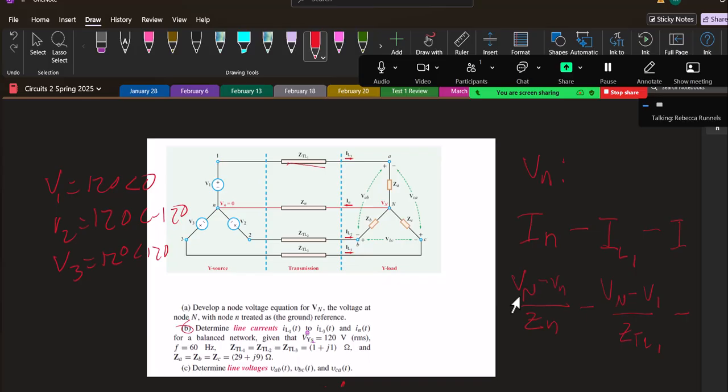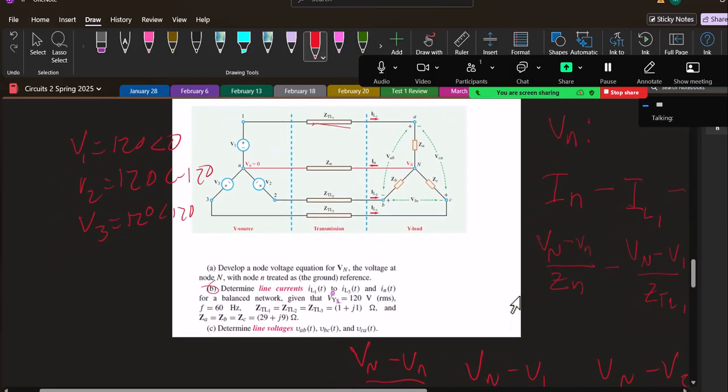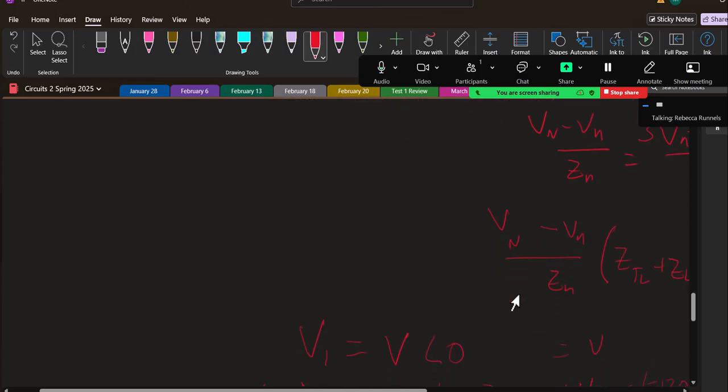I want the voltage between line 1 and line 2, for instance, which would be VAB. We have the currents, so you could go in across the load to A and find the voltage drop, and do the same for B, and find the difference. Notice you have to be a little careful here because our ground is right in the middle.